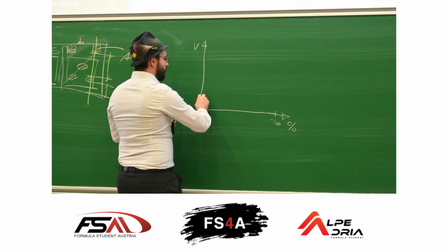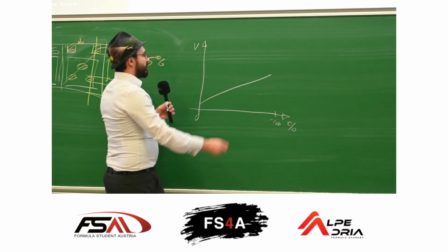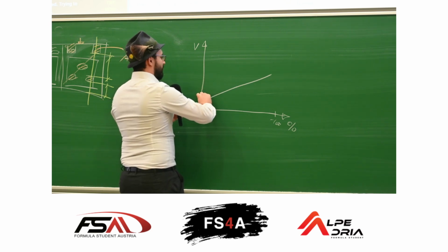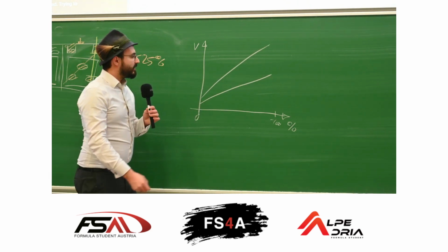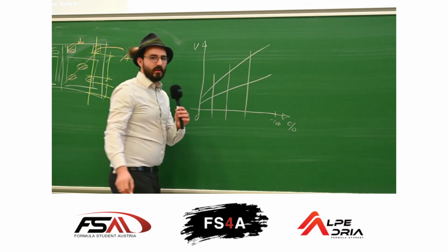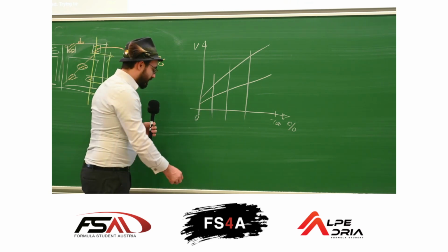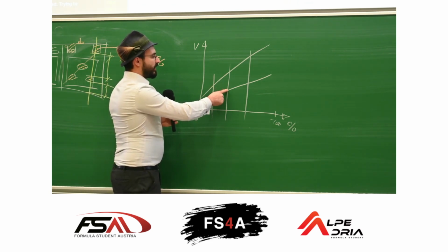You need one sensor which is like this, for example, and a second sensor which goes, for example, like this. The reason behind it is that at no point of the throttle position do you have an intersection between the two signals. At every point you can tell, okay, this sensor should be here, this sensor should be here, the signal is okay.